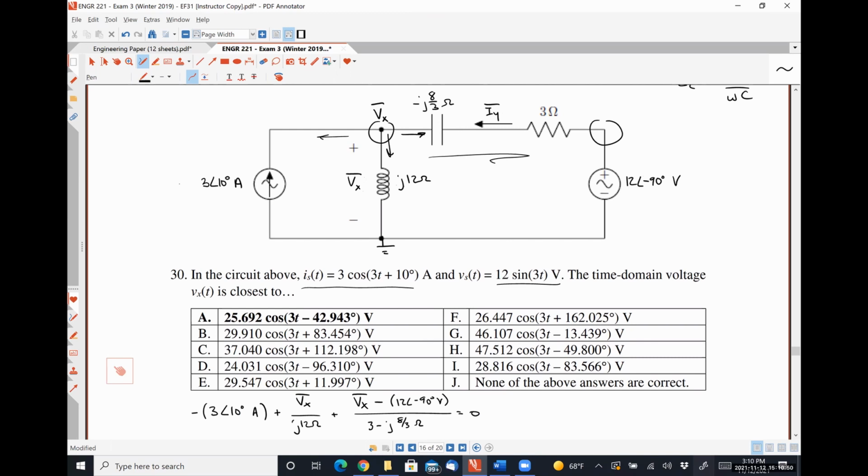We combine those two impedances together to effectively eliminate this node here in the middle so that we could set up a system that only has one unknown quantity, Vx. We did this on that one day when I worked that same problem like 5 different ways. That was another way that we could have approached that.